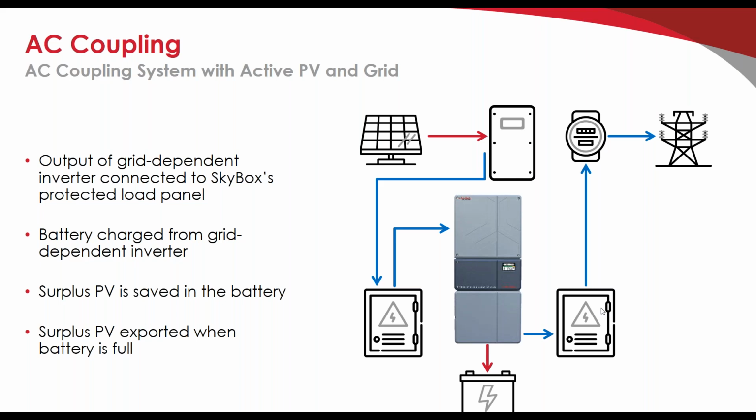Craig asks if SkyBox will work well with SolarEdge's grid-tied inverters installed in 2017. The answer is, as far as I know, yes, because those are all UL 1741 compliant. The easiest way to check would be to look up your SolarEdge model number and spec sheet. But we've done that a couple different times with a couple different customers, and yes, that should work. That works perfectly fine.